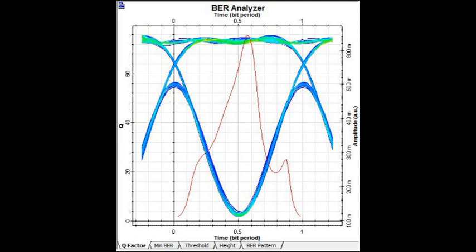When the attenuation value is changed to 25 dB per kilometer, the value of the BER analyzer decreases to 67.6834 for Q factor and 0.834713 for eye height value. The eye diagram revealed that if we increase the attenuation value with the same system configuration, the result becomes low performance because the BER analyzer value of Q factor keeps decreasing. So that's all the analysis result that we can make from this 3-circuit output.